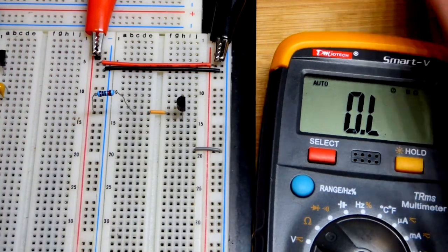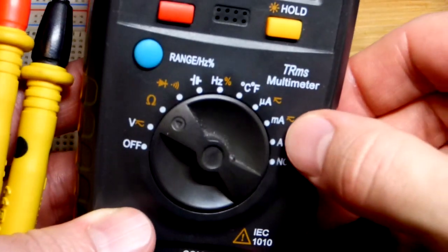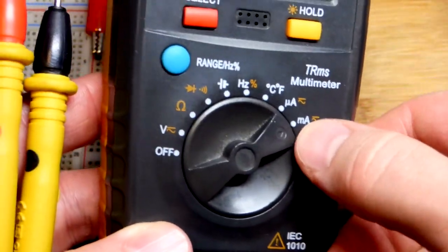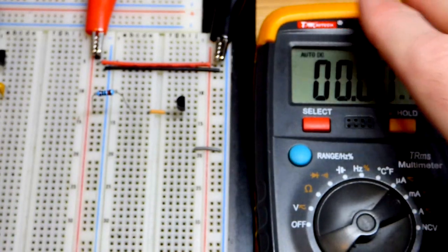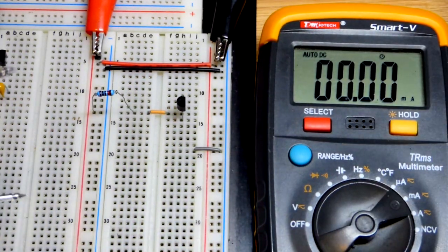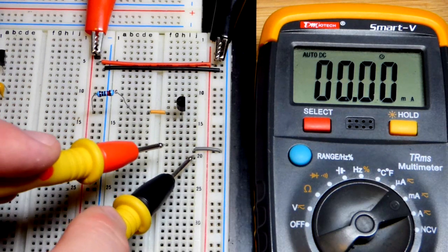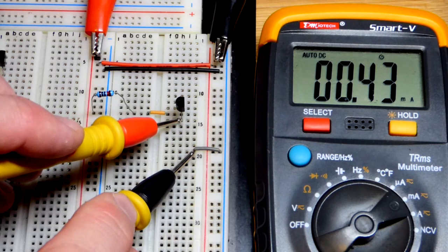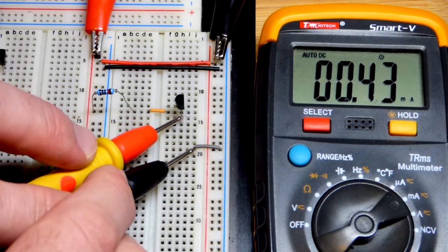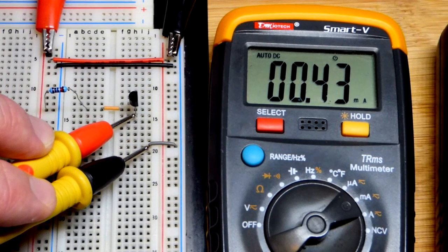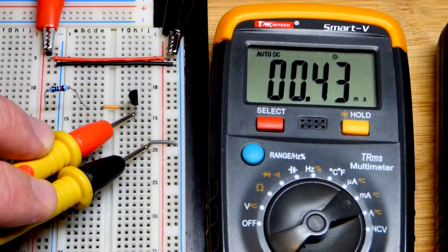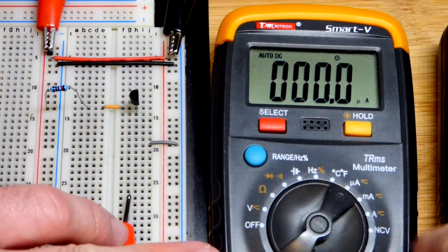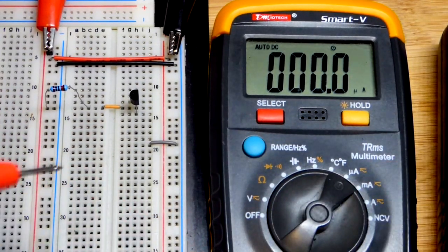Now we can measure the current, and this is where you have to be the most careful. It'll be below the milliamp range, so let's go to milliamps. If we thought it'd be low microamps, we could go to microamps right away, but it's a good idea to start with milliamps if you think you might hit the milliamps. Now we're going to go to the emitter. We have to complete the current path. I'm pretty sure you could see that, but just in case, you can see we got the current that I estimated, the 0.44 milliamps. If you need more precision, you can go to microamps and measure that right there.